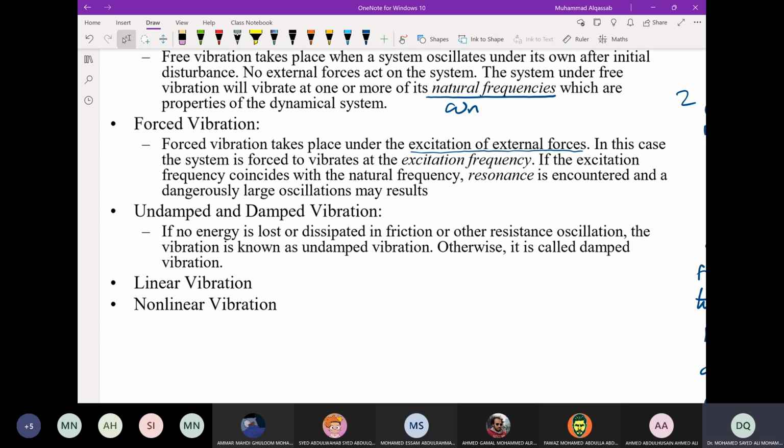Okay, vibration is always measured from equilibrium. It is not neglected, but if you want the total deflection, you should consider the weight. But usually in vibration, we consider the 0 line to be the equilibrium line, and then the vibration is the additional motion only.